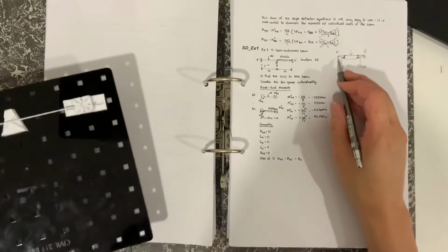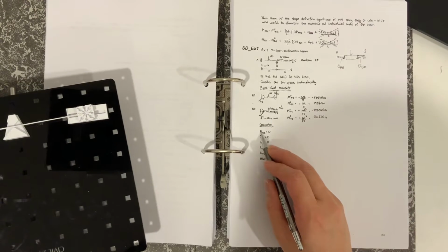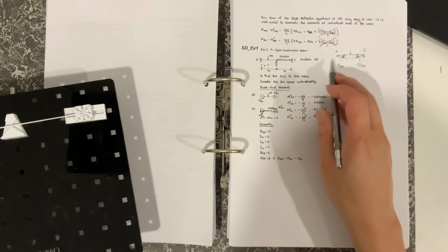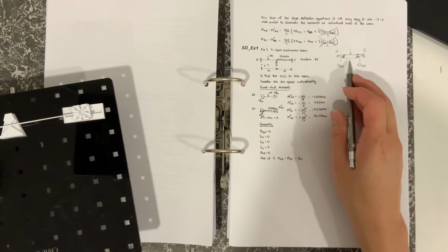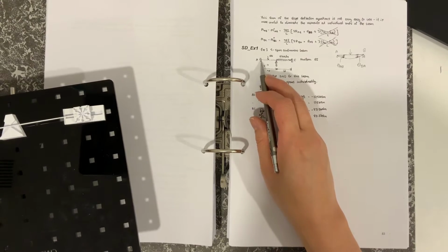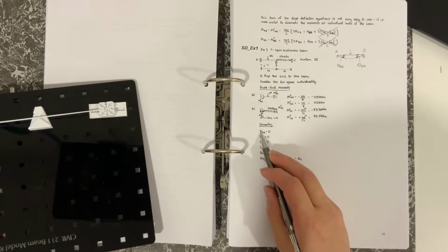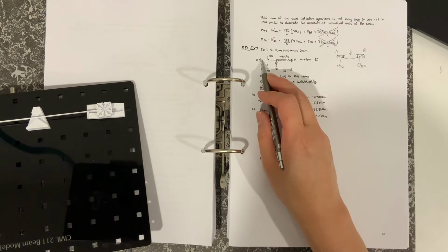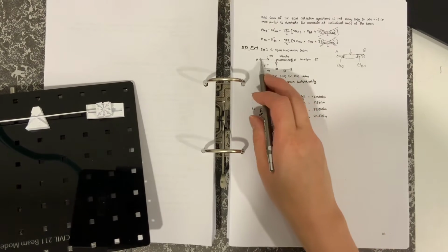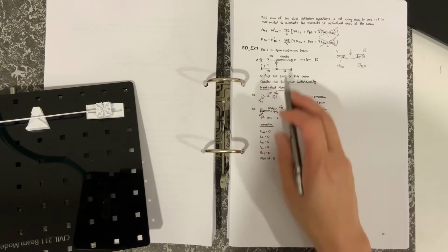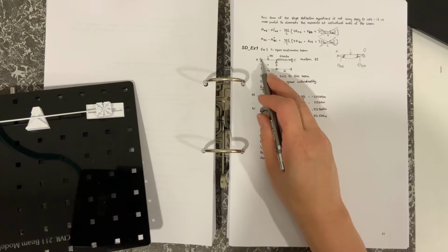In the case of a fixed support, theta AB is going to be equal to 0. When one end is a pin, there is a rotation, but in this case, being a cantilevered or fixed end, there's going to be no rotation. So from the geometry, theta AB is equal to 0, the rotation at that point under this system of loads, or because of the beam itself, is going to be none.